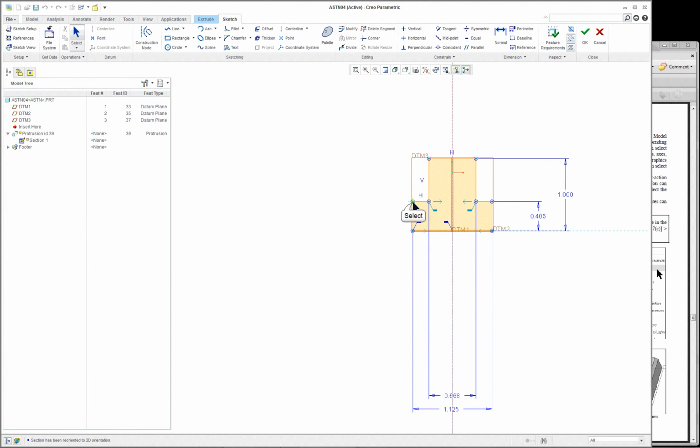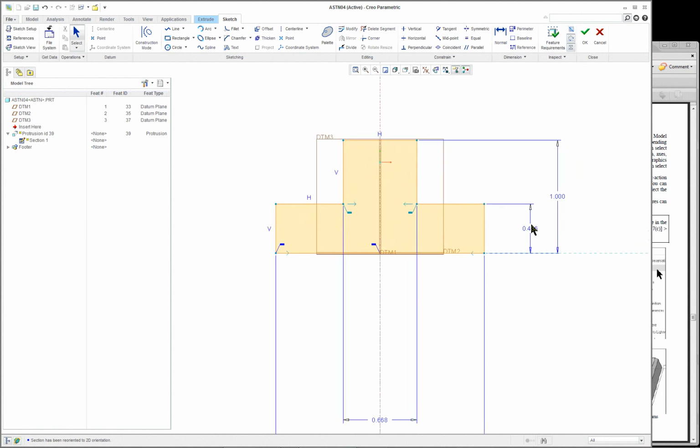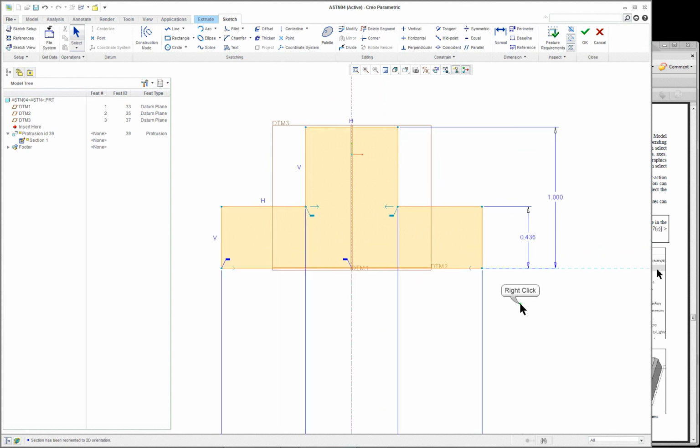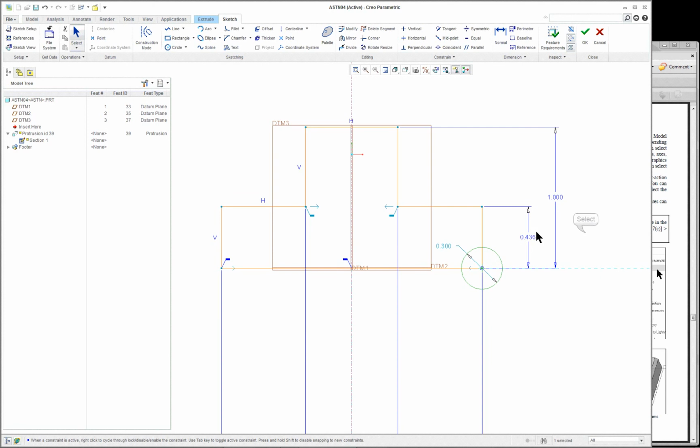That's true. So for instance, I can change some stuff by dragging it. But normally you'll go back in here if you want to do something with the geometry itself. You want to make the geometry different or add some sort of geometry to it. For our purposes, let's right mouse button and click, how about circle? And let's put a circle on the very bottom here, like so. Middle mouse button. Now it's not shading because it's over the top. Middle mouse button, left mouse button.